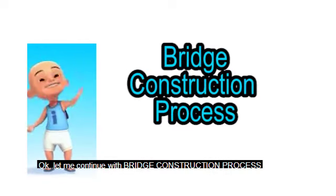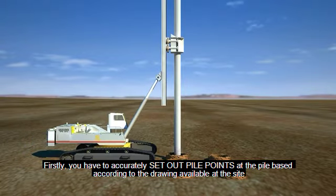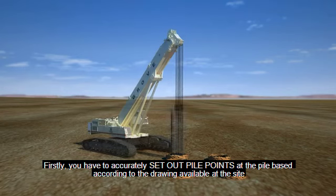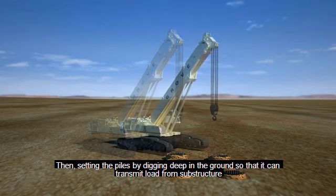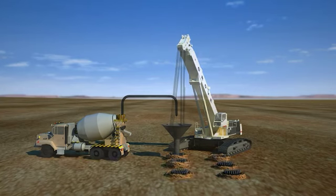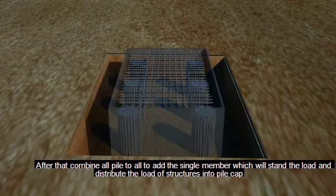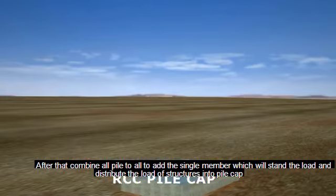Okay, let me continue with the bridge construction process. Firstly, you have to accurately set out pile points at the pile base according to the drawing available at the site. Then, setting the piles by digging deep into the ground so that it can transmit load from the substructure. After that, combine all the piles into a single member which will stand and distribute the load into the pile cap.